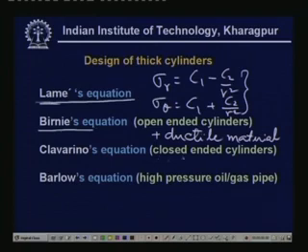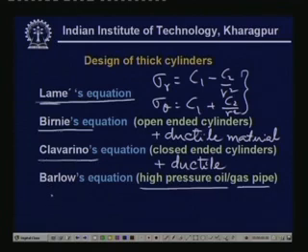If the cylinder is closed-ended and the material is ductile, then it is governed by Clavarino's equation, and for high pressure oil or gas pipes, the design is guided by what is known as Barlow's equations. So, now let us see how to get the proper thickness of a thick cylinder which is subjected to internal pressure.